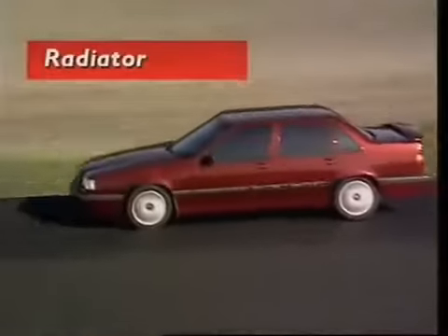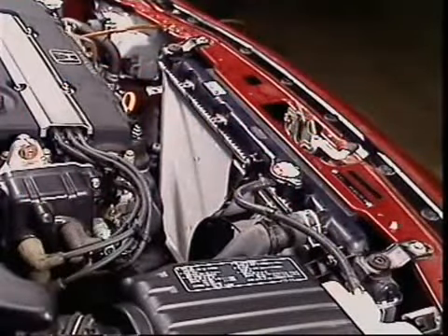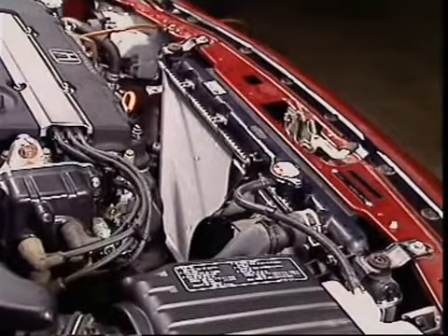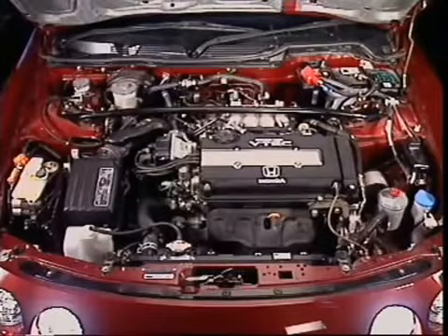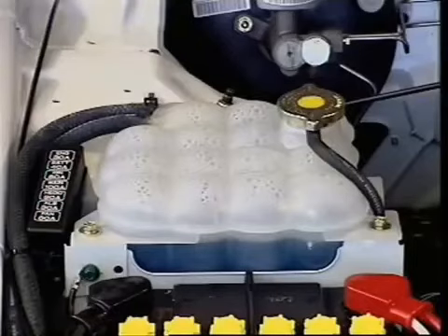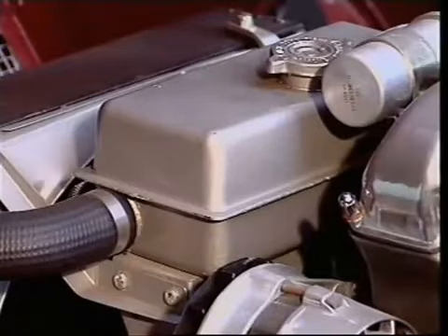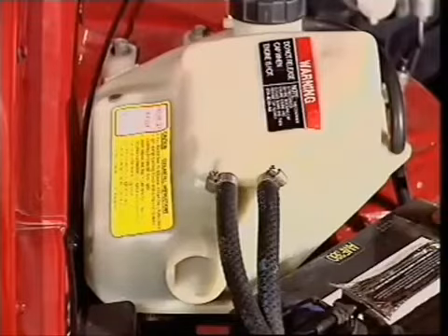Many radiators are mounted at the front of the vehicle in the path of greatest airflow. The air carries heat away, cooling the liquid before it returns to absorb more heat from the engine. Where a radiator is mounted also depends on space, how the engine is mounted. A header tank can be mounted away from the radiator, where it provides a coolant supply stored above the engine. It can be made of sheet metal or hardened plastic.